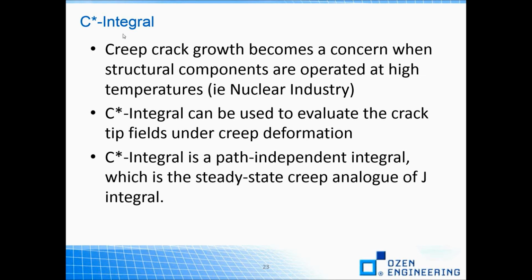This is one parameter in fracture mechanics that helps in assessing materials at high temperature. The C-star integral is a path-independent integral like the J integral, which is the steady-state creep analog of the J integral and could be useful as a creep fracture parameter.